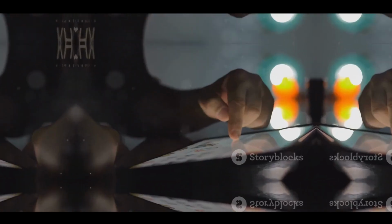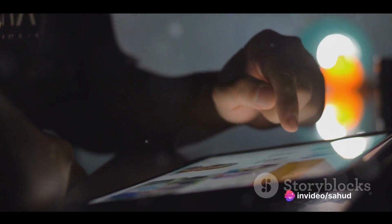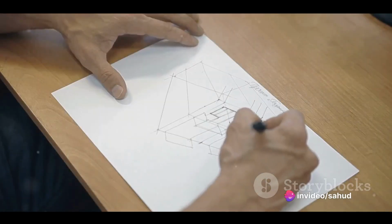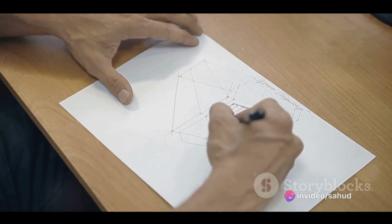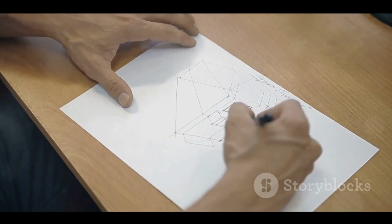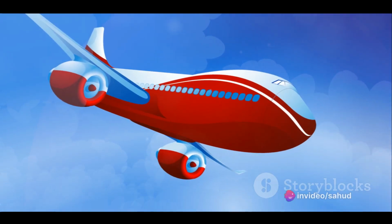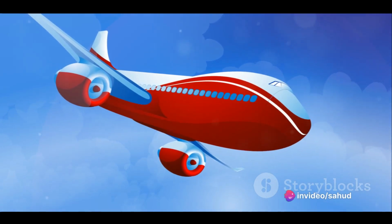Stay tuned. Creating your first sketch is simpler than you think. Let's dive right in and get our hands dirty. The first step is to select the sketch plane. This is the canvas where all your design dreams will take shape. SolidWorks provides three default planes: the top plane, the front plane, and the right plane. For our exercise, let's select the top plane.